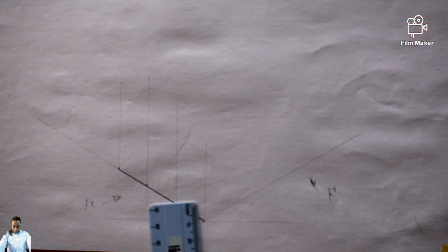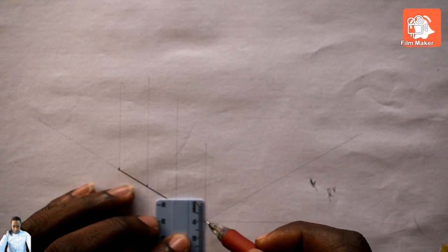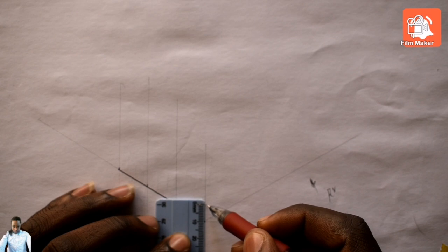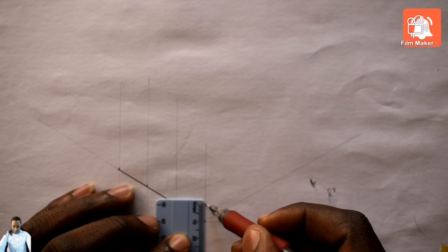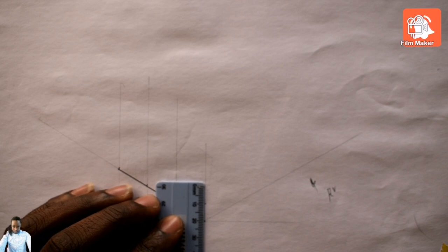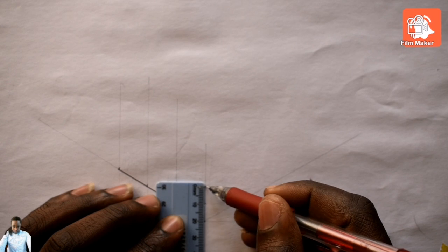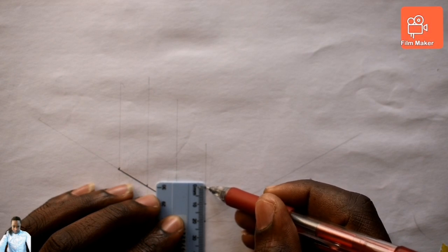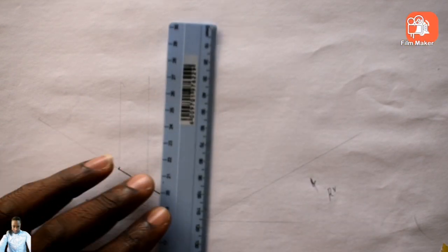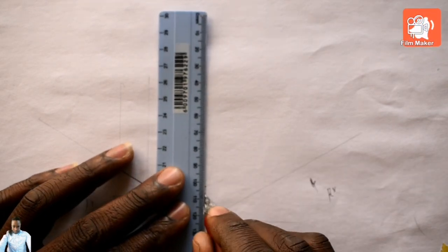But remember we are using an enlargement scale. So from here is the first 5 millimeter, which is going to be 10, and where the first one ends begins the second one, the second 5 millimeter, which is the 10. So now I have it dark as well.